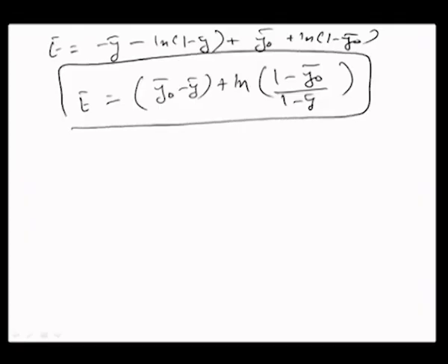So that's how the time ratio can be expressed in terms of the length ratio, where this ratio is with respect to the equilibrium gap ye, and the time ratio is with respect to the amount of time which is needed by a tool going through a feed f with respect to the workpiece to cover that equilibrium gap ye.